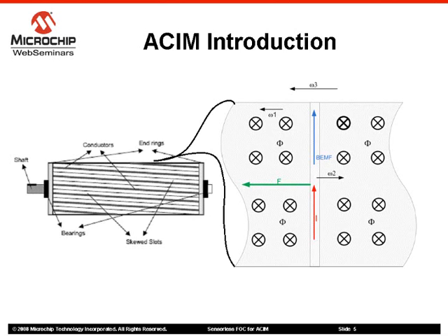The resulting conductor speed relative to the magnetic field speed is omega 2, which is equal to omega 3 minus omega 1. A back electromagnetic force, also known as back EMF, will be induced with the direction of the blue arrow indicated in the figure. If the relative speed of the conductor with respect to the magnetic field speed is 0, no back EMF will be induced, and therefore no current will appear inside the conductor. The interaction of the current with the magnetic field will produce the electrodynamic force, F, shown with a green arrow.